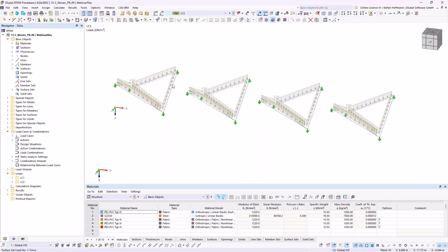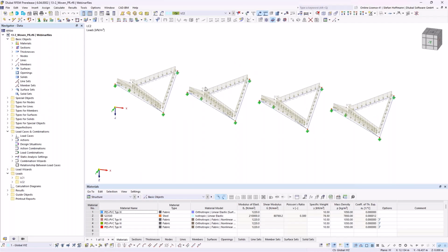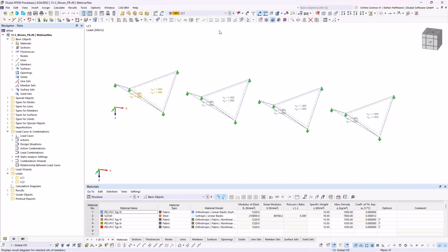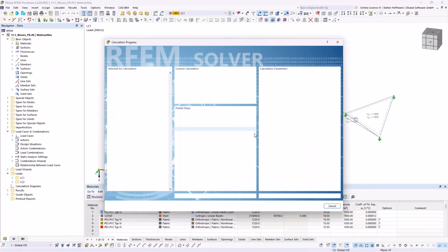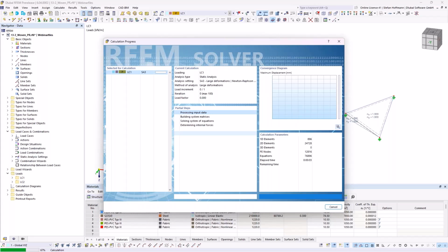And then there is a prestress we are giving, just a normal symmetric prestress into local X and Y direction with the standard method, so nothing special. And we want then to load it with a vertical load, because doing the prestress, so the form finding for the structure, we most likely define the shape we want to reach with our inner forces.